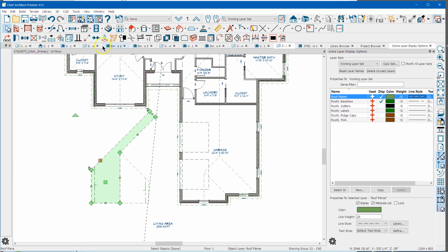And I've got my edit toolbar up here. Normally it's down here at the bottom, but I just moved it up here at the top. And somewhere in your edit toolbar, I think you'll have this command right here. This is intersect, join two lines. If you don't have that, I'll show you how to do it manually, but all I'm going to do is select this line here, and I'm going to select this tool, and I'm going to select this edge over here. And what that does is that joins this line with this line, effectively just chopping off that tail. I'm going to undo.